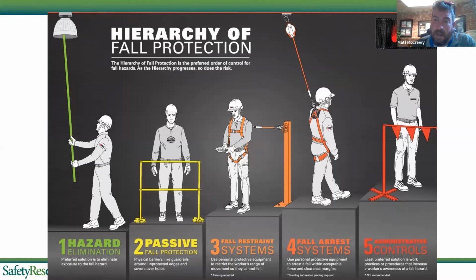And then if we're using rope and rope grabs, okay, so let's say my anchor's 10 foot back and I set my rope grab for 9 feet of slack, that is fall restraint. If I have 9 feet of slack from the anchor point and I'm 10 feet away from the roof edge, I am compliant with fall restraint. However, if I start going left or right and working at an angle, my slack turns into 12, 13, 14 feet. And then inevitably the person performing that work is going to go back to that vertical line. And instead of having the 9 foot of slack for the 10 foot leading edge, they're now going to have 14 foot of slack. And now we're in a fall arrest situation.